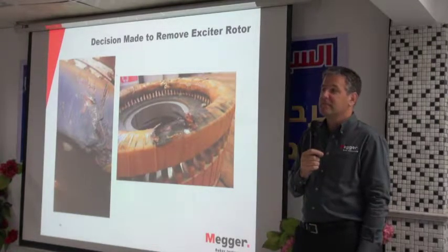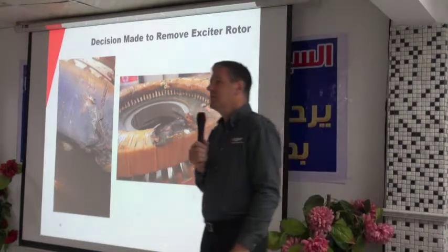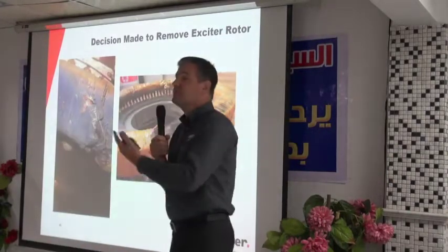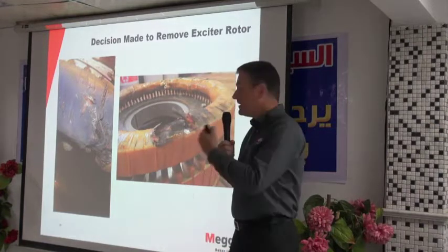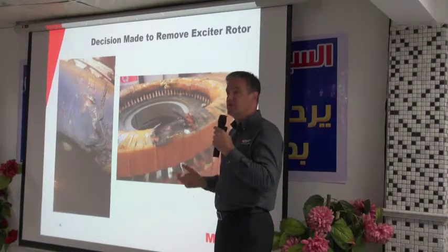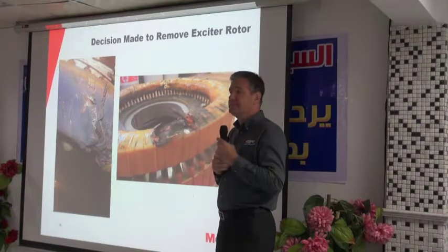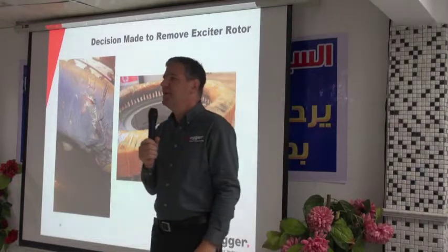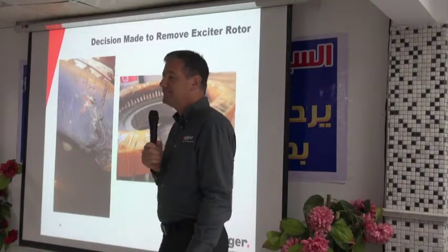How do we remove this fault? Sorry? How do we remove this fault? You have to rewind completely. Take out the windings and make a new winding. No other possibility. Not use this winding. No, new winding, completely new. Yeah.